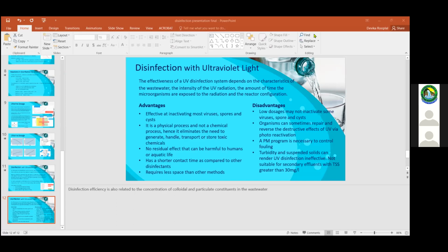Where do you start? So that will basically be a sort of trial and error, or some bench-scale laboratory testing where you have samples of your water. You do this benchtop testing. I'm not sure if you're familiar with this jar testing procedure where you take samples of your water. It's on a smaller scale, but you basically simulate your plant. So you have an idea of what you should be dosing to give you that residual. So let's say